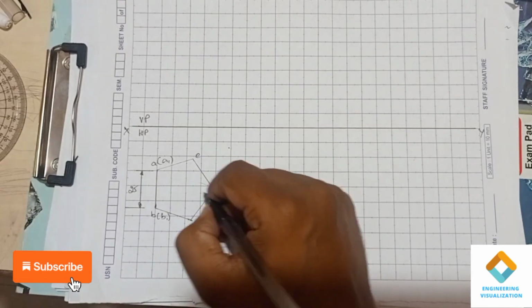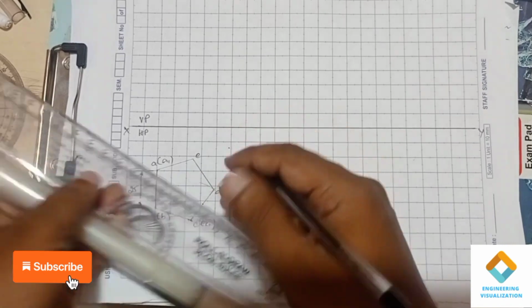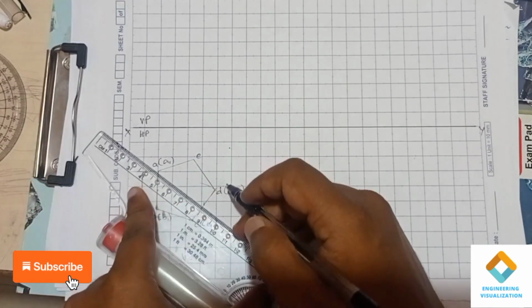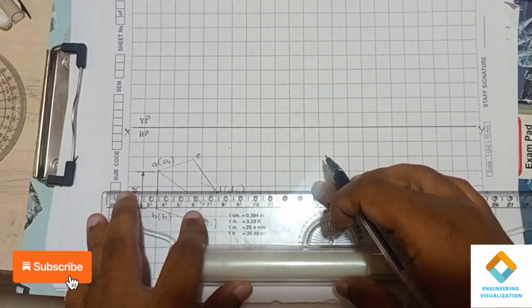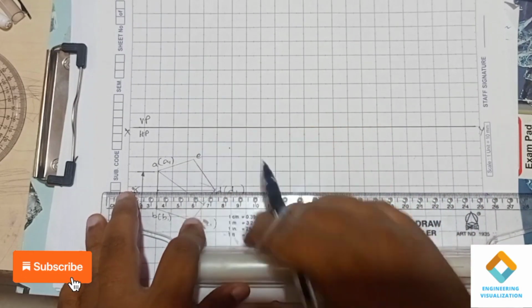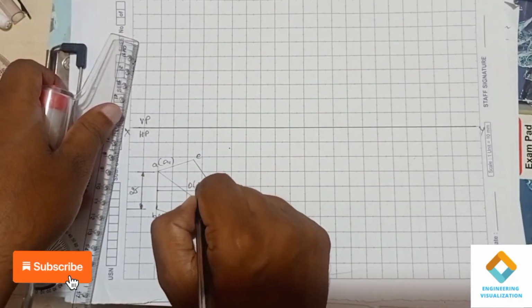Now we have to draw a perpendicular bisector here. I'll be drawing two perpendiculars. You know how to draw. First mark the midpoint of the edge and try to connect with the opposite corner using a straight line. Marking the midpoint and then connecting with the opposite end, you will get the perpendicular bisector. Now we are getting the center, that is O1.